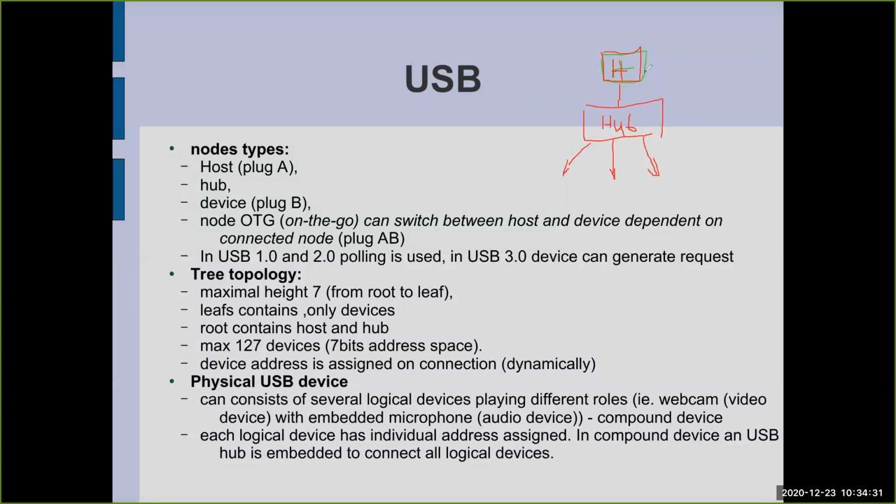So let's say we have a single host, so a single USB controller, and the serviceman knows that to this controller there is a hub, and the keyboard is connected, and a single external port is connected. So if the keyboard doesn't work and you connect a mouse or other device to that particular port and it doesn't work, it means that something is wrong with the hub.